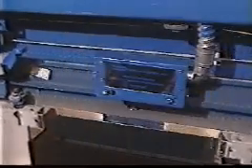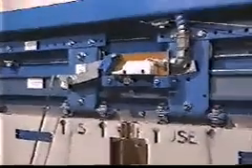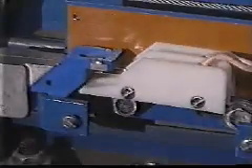Next, we will look at elevator door operation and the differences between hoistway doors and car doors. The hoistway doors are located at every landing served by the elevator. They provide protection to the public when the elevator car is not at that floor. Every hoistway door must be equipped with an interlock safety device. The interlock locks the hoistway doors and in doing so completes an electrical circuit that allows car movement.